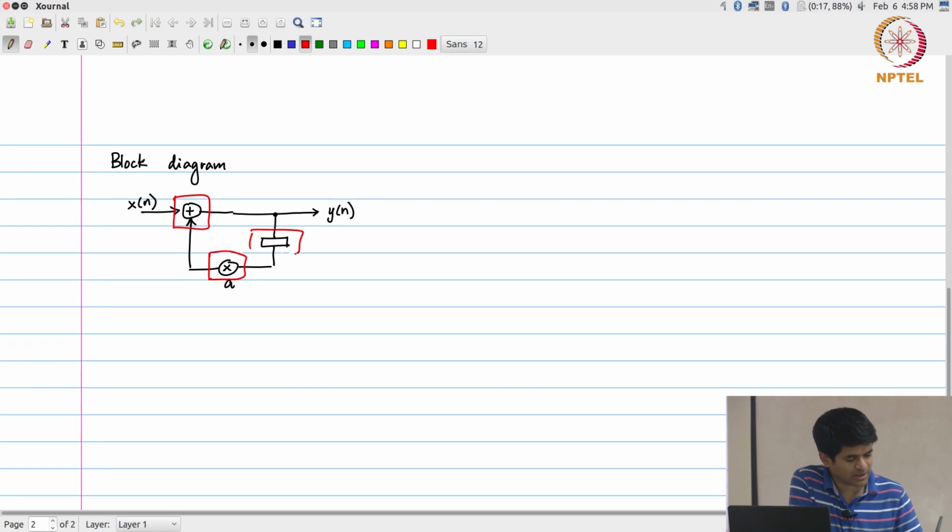These are functional blocks, and we have the wires that are essentially drawn as circuit-level connections between them. So you can instantly recognize that this is very close to a hardware representation. This is directly saying this is how the hardware will look. If I had these blocks, a register, a multiplier, an adder and so on, I could directly implement this in hardware by wiring this up together on a circuit board. What would the FIR filter look like for this?